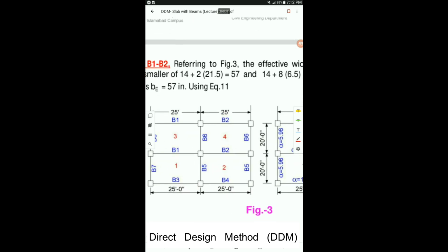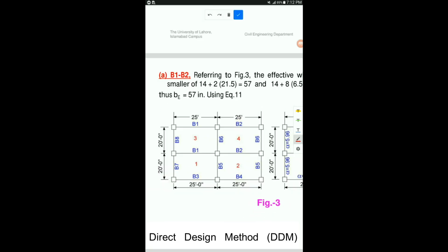Okay, let's look at this example. I'll just focus on this, the one I'm highlighting right now. This first one is called the exterior support. This one is called first interior support, and it has two faces. The face at this point is called the exterior face of first interior support, and this one is called the interior face of first interior support.